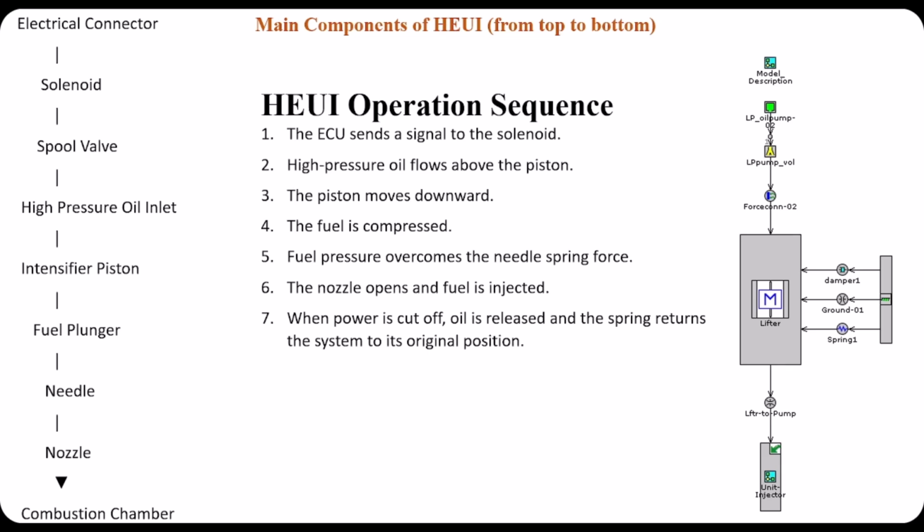And about downstream of the pipe is the valve solenoid connection object that controls the flow into and out of the high pressure pump chamber. The high pressure fuel from the pump chamber goes to the injector section of the unit injector system. The high pressure pump plunger displacement is achieved through a hydraulic force generated by a low pressure oil pump system.